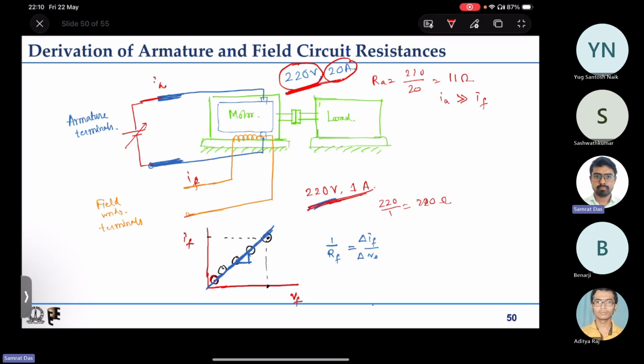That is the point. These ratings are for the operating condition when the motor is rotating. Motor rotating and field winding excited means there will be some back EMF, so most of this armature voltage is required to oppose that voltage.